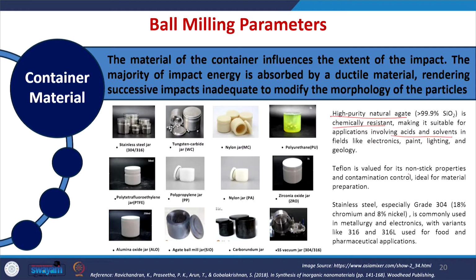If you want to work on non-stick properties of the material or reduce contamination, the ideal choice is a Teflon container. We can also use a stainless steel container, depending on the final application. If it is for metallurgy and electronics applications, we can go for grade 304, and if it is for food and pharmaceutical applications, we can go for grade 316 and 316L.